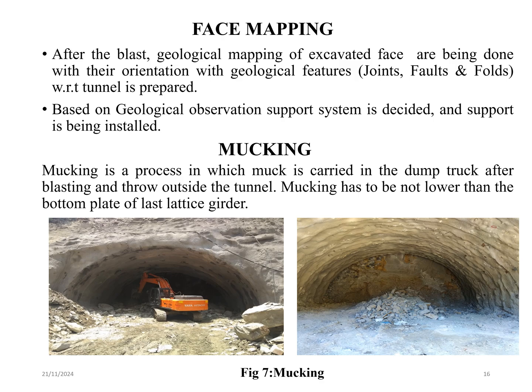Mucking. Mucking is the process of removing the broken rock, which is also known as muck, from the tunnel after blasting. Dump trucks are used to transport the muck outside the tunnel. This step is essential to clear the tunnel for further excavation and support installation.